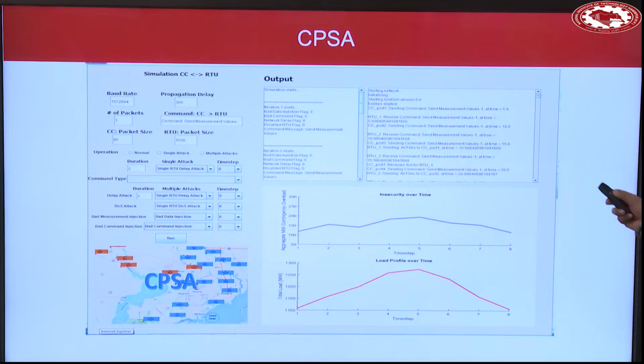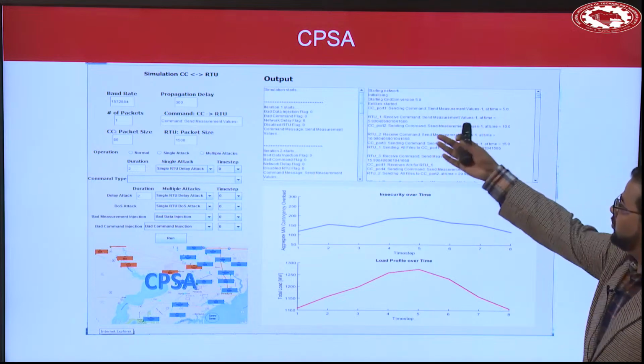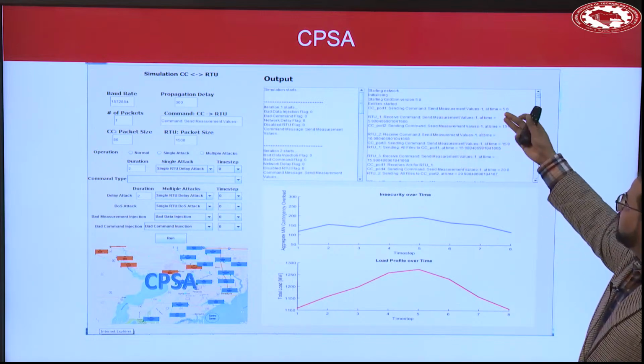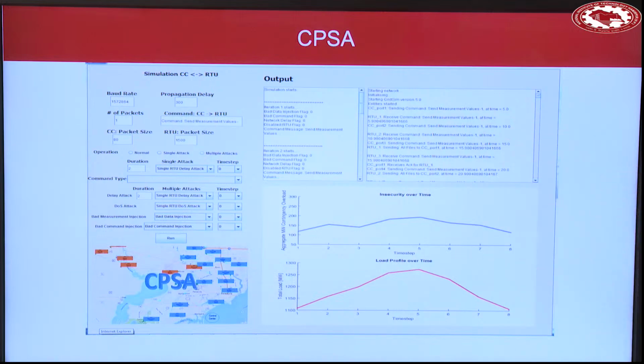Right, so you can create a log in terms of the control center, this port connected to this substation, this particular RTU, at this time. You can see the size and everything. And in a way, you can also derive how long it takes to send or receive a packet. Again, they are not always constant, but you can get a sense between this and this. It takes roughly 2 minutes, roughly 10 minutes. And this is what the normal scenario looks like. I'll be talking about that in other slides.